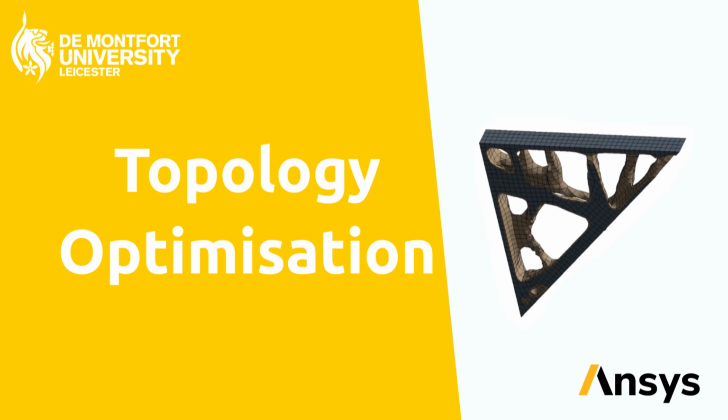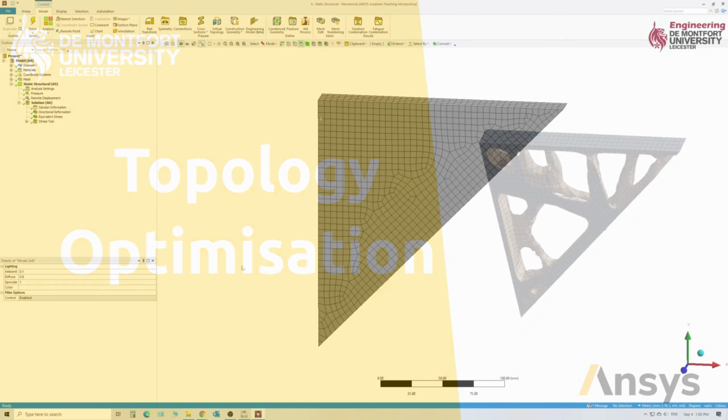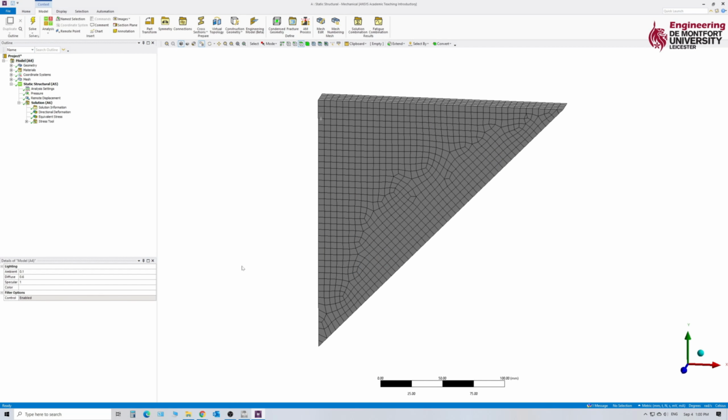In this video, we're going to be exploring how we can perform a topology optimization using ANSYS. So on the screen, you'll see that I've got a basic component. This is designed to be a bracket, and its height's 200, its length's 200, and its depth's 20 millimeters.